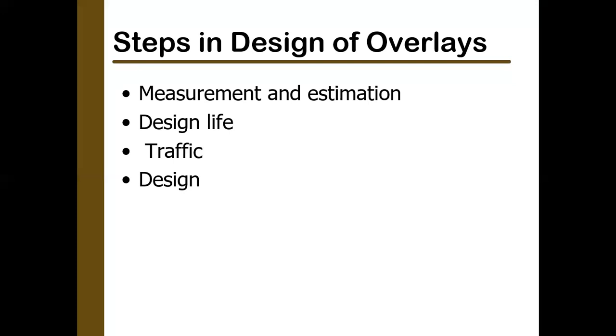Normally, if the value of the pavement condition index is below 30, it means you require an overlay. So this is one way.